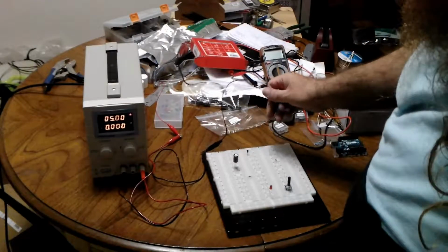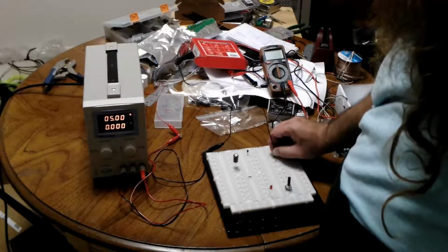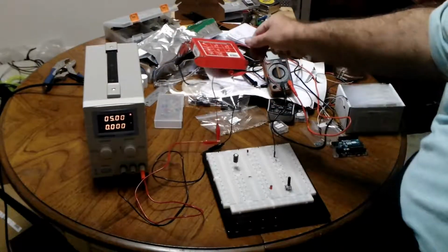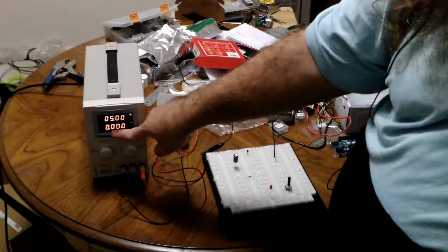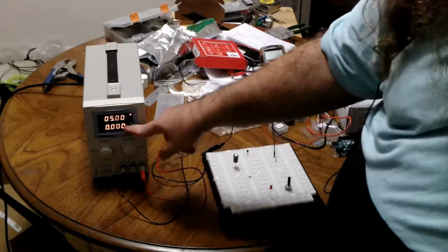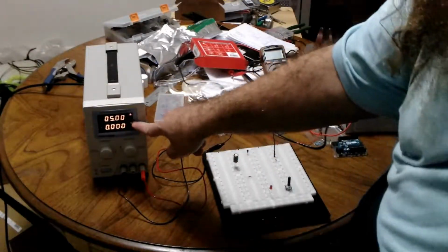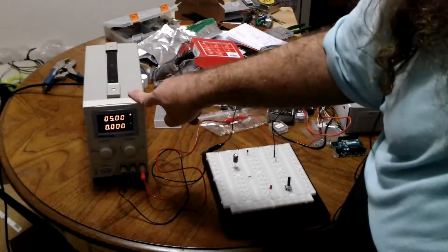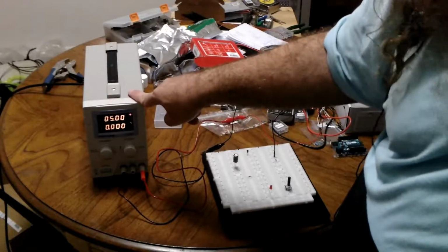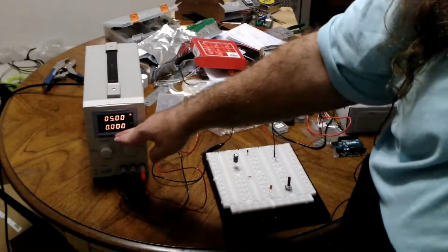So if I connect the negative power to one side of the non-polar capacitor, it doesn't matter which, and then the positive, the voltage is going to climb and climb until eventually it'll reach 5, it'll stop, and this will go down to 0. It'll stay at 1. So it's turning the voltage up and up. But what happens? When I connect this, it's immediately going to draw lots of current. And this thing is going to say, hey, he wants a maximum of 1 milliamp. So it's going to turn the voltage down real quick to make sure only 1 milliamp is flowing.